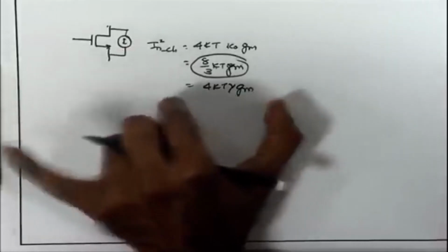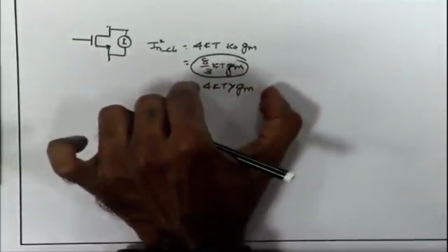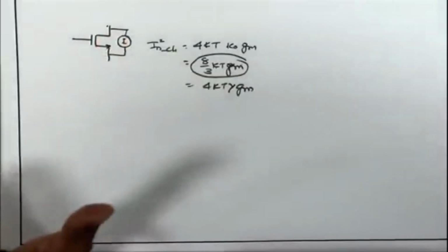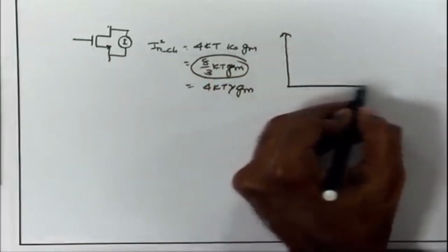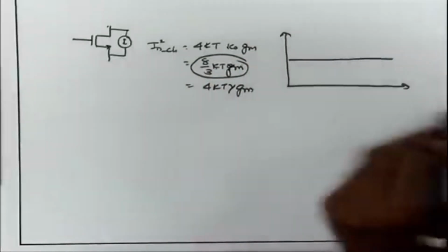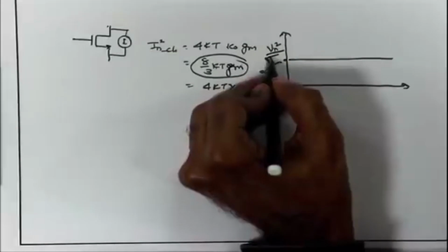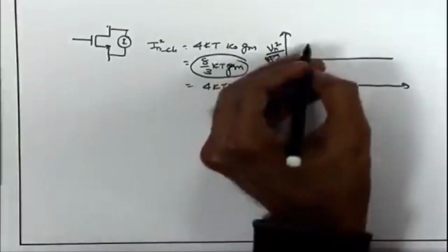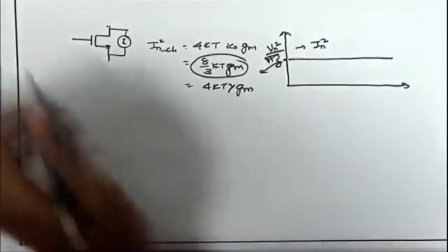So, this is similar to the resistance case, where this channel noise current is coming because of the resistive conduction path between the drain and source of the MOSFET. And just like the resistor, this is having the white spectrum. So, once again if I talk about this noise, this is again having a white spectrum, and the magnitude over here, I n square per hertz, is denoted by 4 kT gamma Gm. So, this is basically I n square, the RMS or mean square value.